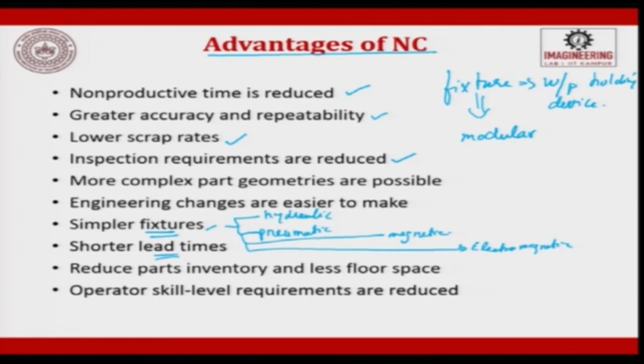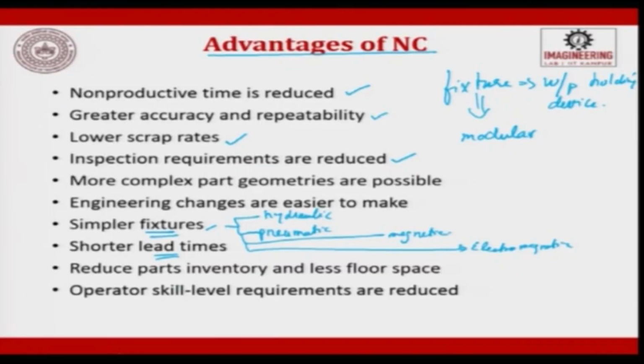Biggest advantage of NC, shortening the lead time. Moment the CAD is ready, the program gets ready, the part gets executed. Earlier the process planner sits and understands the drawing, then he tries to write a program or then he tries to arrange for all the fixtures, everything and then get done. So, the lead time is reduced.